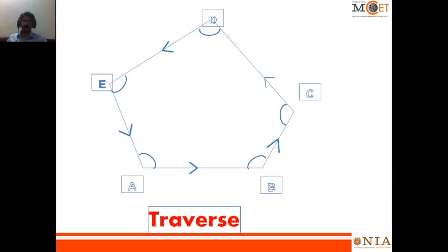This figure shows a closed traverse. So here we have to determine these angles, but the compass won't give these angles directly, right? This traverse starts from A, keeps on moving and ends again at A. So this traverse is called a closed traverse. If it ends at E itself, or it moves on in a different direction, then it is an open traverse. Only if it gets closed can we determine the area.